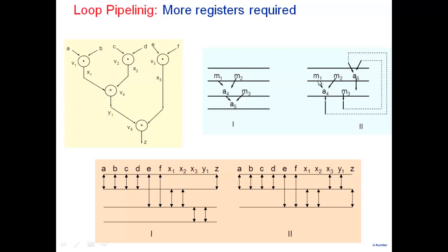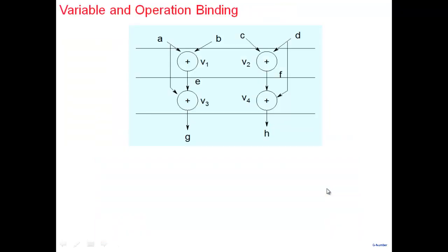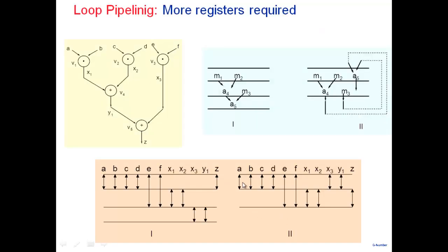If we look at this one, again we go back and look at M1, M2 and all that. We fill up this chart here. We find here how many do we require? 1, 2, 3, 4, 5, 6, 7, 8. 8 registers are required. So here 8 registers you'll have to provide in order to store the relevant variables.